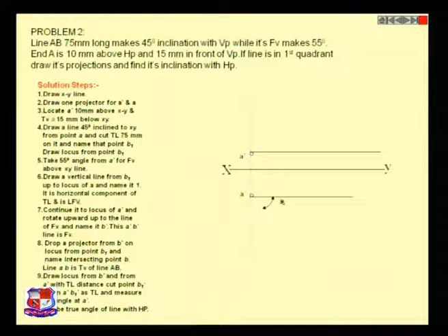Mark angle of 45 degrees from the point number A and draw a 75 mm long line like this. Name it as B1. It is the true length. If we had the angle with the horizontal plane, then it would be the same problem like the last one. But here is the catch. We don't have this angle with the horizontal plane.